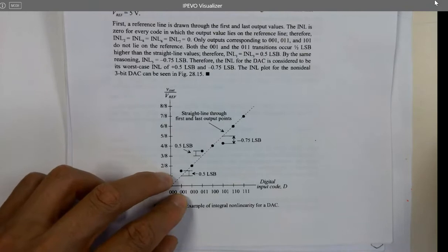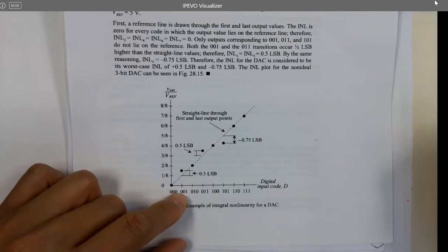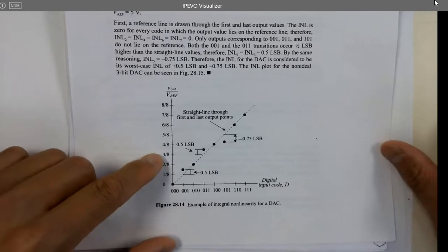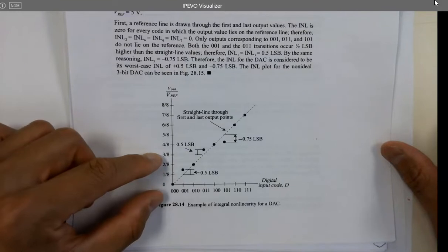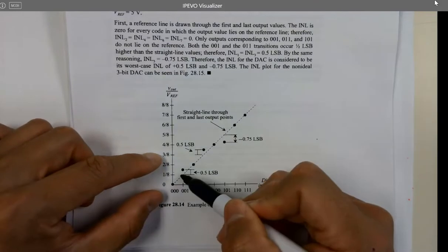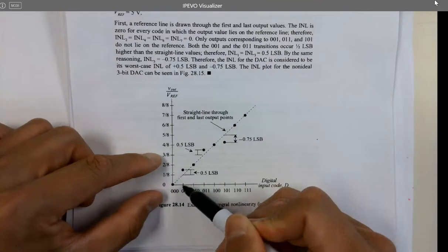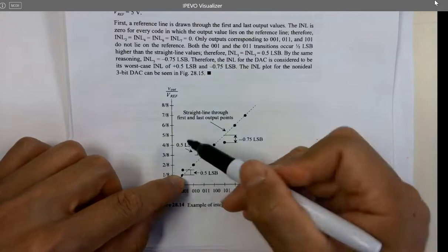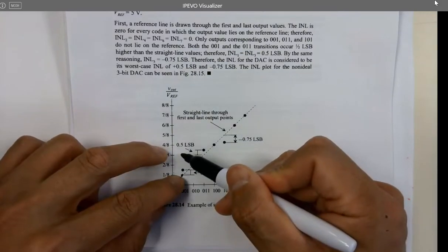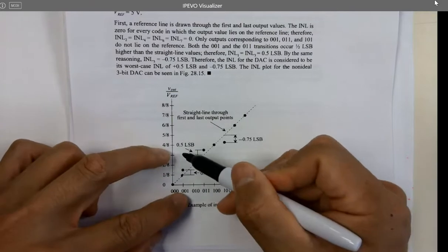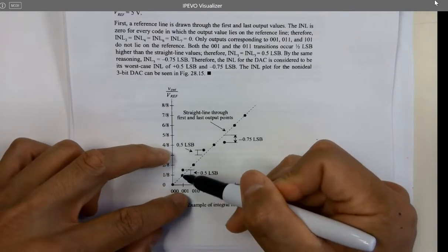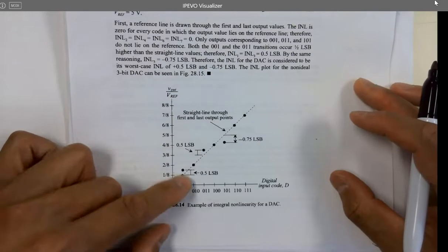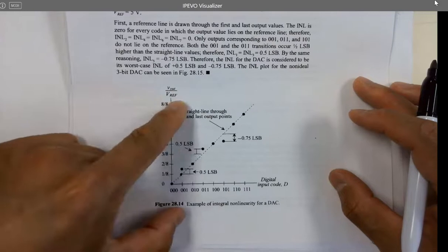Does that make sense? So if that first point was at like 3/8, we could have 3 LSB. It's going to be 2 LSB INL, because you are supposed to have 1 LSB. The dashed curve is the ideal curve, right? So for one input, you are supposed to get this, ideally. But if it jumps to here, then your INL1 becomes 2 LSB. Make sense? It can be more than 1 LSB because it can be anywhere, depending on the design.